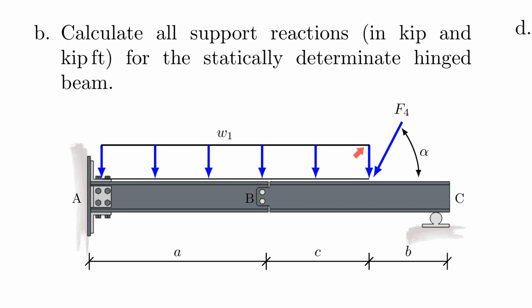I know that students are sometimes confused about the fact that it goes through, but just release the system either on the right side or on the left side, and just include everything to the right or to the left. You also have this force on an angle, so that of course means that there must be a horizontal component, and hopefully you can identify where that has to be resisted and you can calculate that properly. That is problem number B.